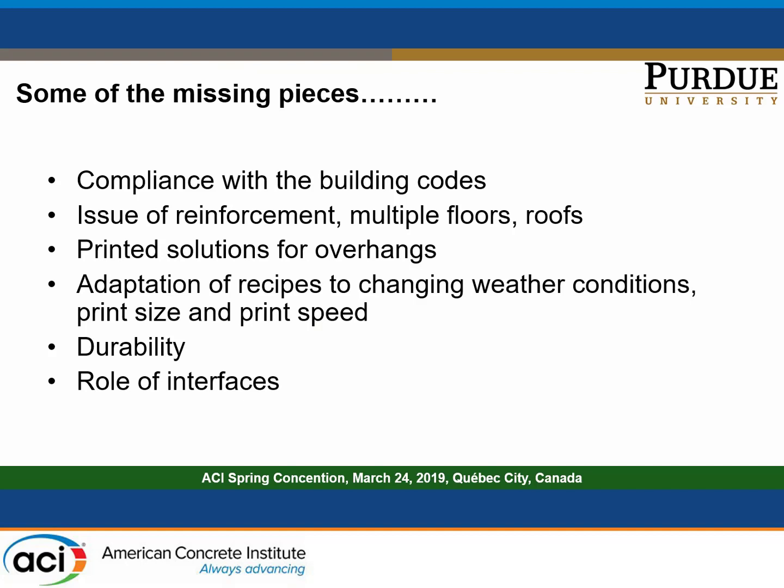There are some important missing pieces in this whole technology. Probably the most important one, and we hear a lot about it at ACI. ACI formed a committee on 3D printing, and one of the tasks that the committee is dealing with is what do we do about compliance with the building codes? Those are very different structures, and we do not have existing building codes that can address some of the issues of the quality of the concrete or quality of the structure with the 3D printed concrete.